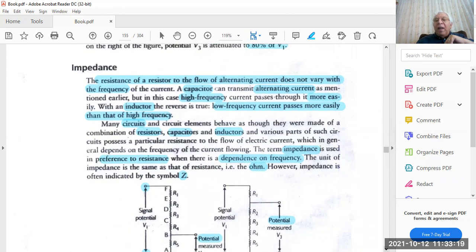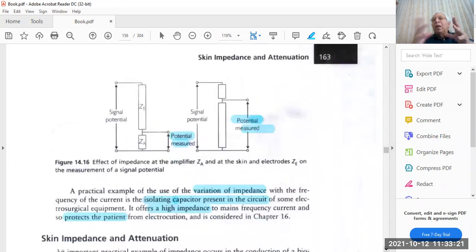most of the equipment used, such as the ECG, has an amplifier with a resistor. Most of them have a higher impedance than the skin impedance. Of course, we are trying to minimize the skin impedance by putting KY gel so that the signal will be much improved. But we are afraid of electrical interference. We're afraid of electrosurgical interference that may cause heat problems.